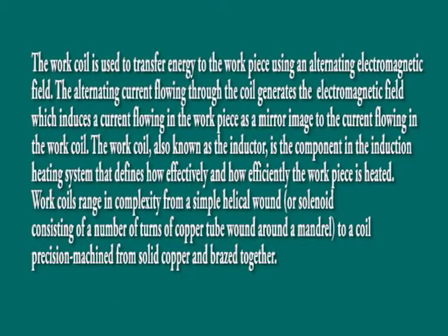The work coil, also known as the inductor, is the component in the induction heating system that defines how effectively and how efficiently the workpiece is heated. Work coils range in complexity from a simple helical wound solenoid consisting of a number of turns of copper tube wound around a mandrel to a coil precision machined from solid copper and brazed together. This can be easily seen in the figure.